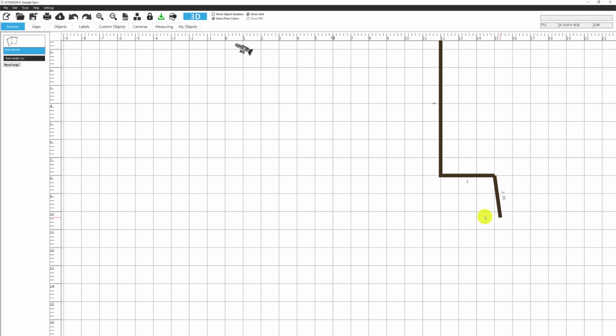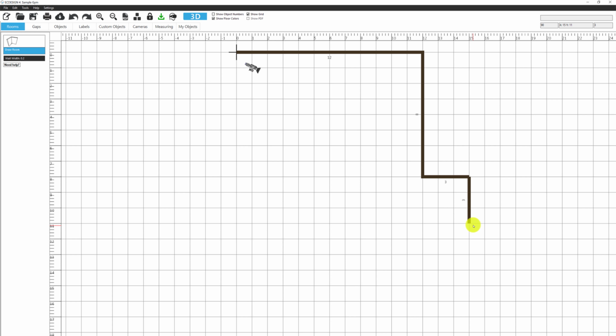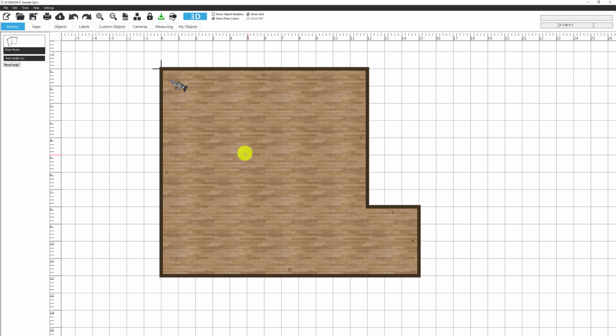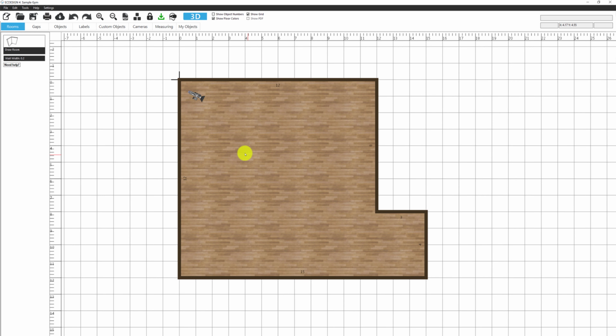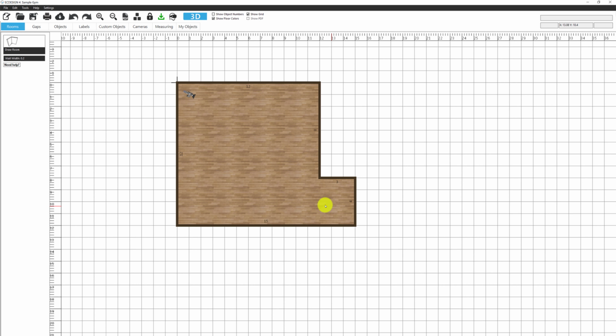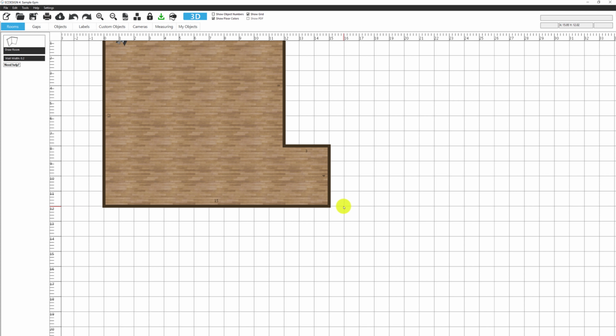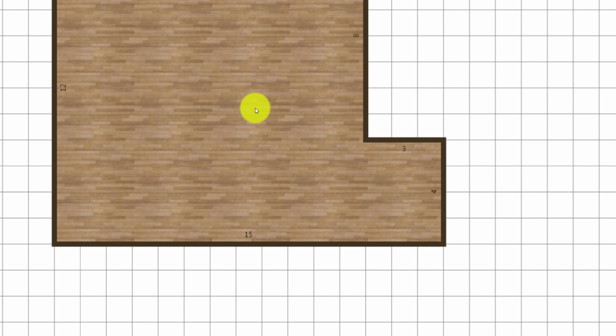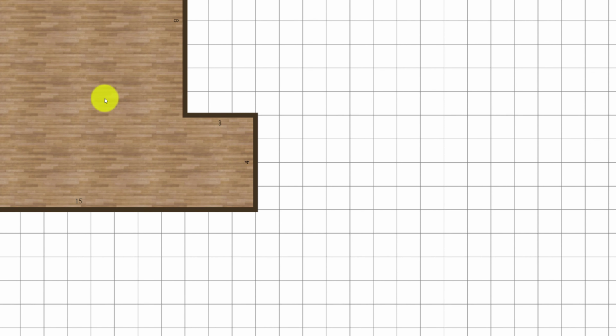So let's move on. And I use my scroll wheel on my mouse to move in or out from the scene. You have red markers showing when 2 walls are parallel. And when we close this first room up, we actually see the floor option that I selected. I can use, as I mentioned, the scroll wheel to zoom in or zoom out, and wherever you place your mouse cursor, that is where you will zoom in or out. If you hold down the right mouse button, you can pan the floor plan as well, up or down, left or right.